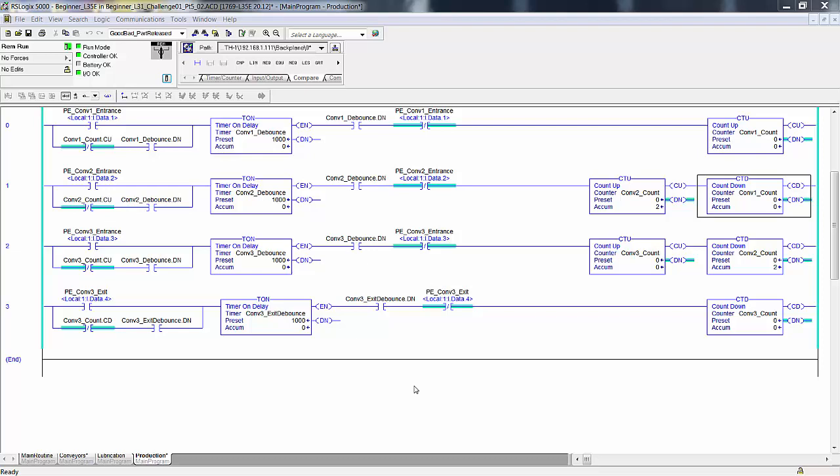From that, then, you get a process design, specifying all of the physical details to accommodate the defined process, the floor space needed, how many stations in the process. If there are no human beings intervening or interacting with the process, then you need less stations. But any place that you need a human being to interact or intervene, you need a station, an operator station.